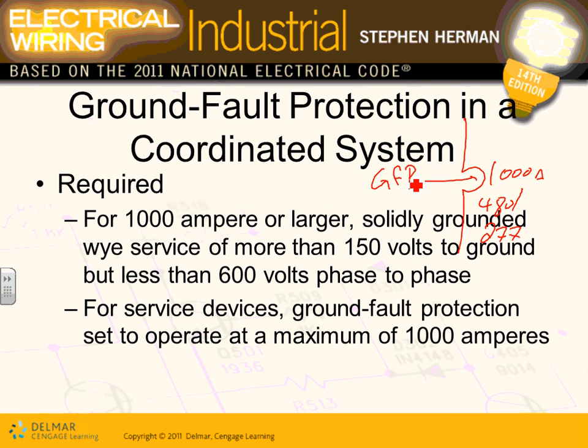The reason that they do it this way, guys, on major electrical equipment, is because if you have 1000 amp 480/277, the ground fault can be so high that it could be very destructive, but that cannot be sensed by the circuit breaker. So you could have a 700 amp ground fault sitting on your system, burning your building, and the circuit breaker sitting there doing nothing.